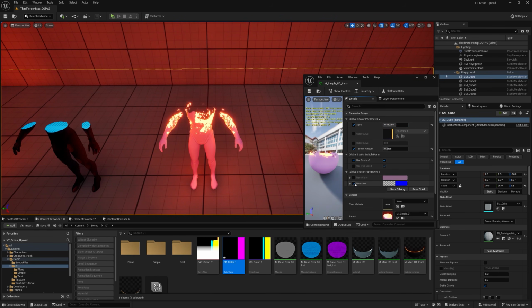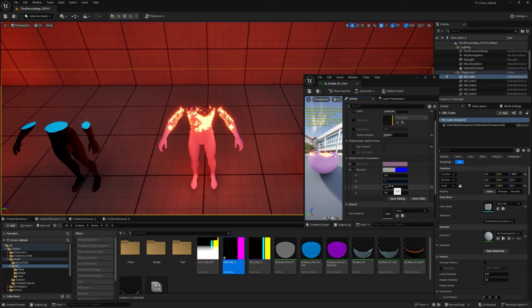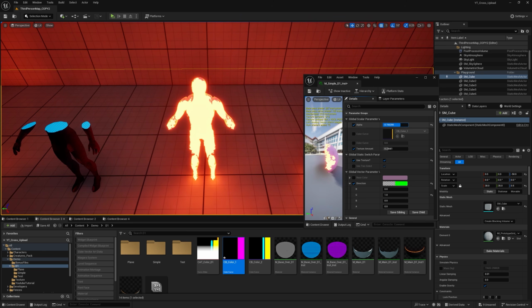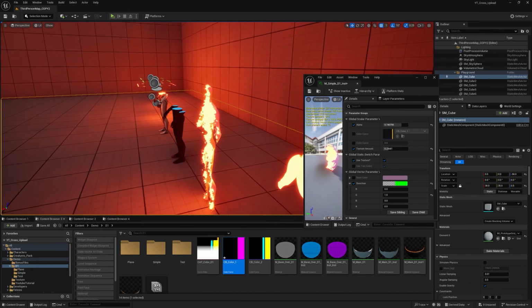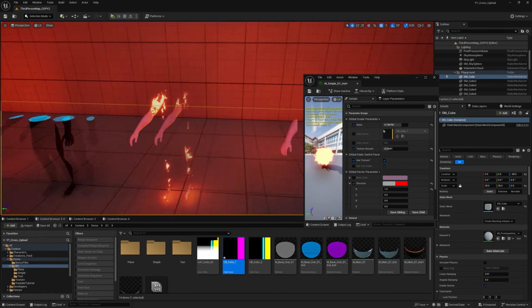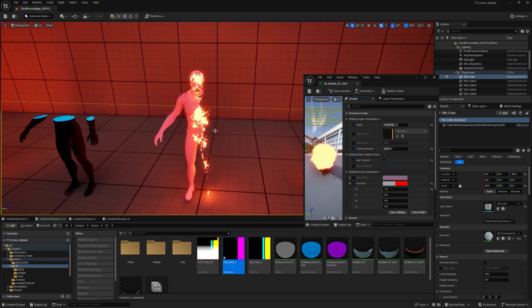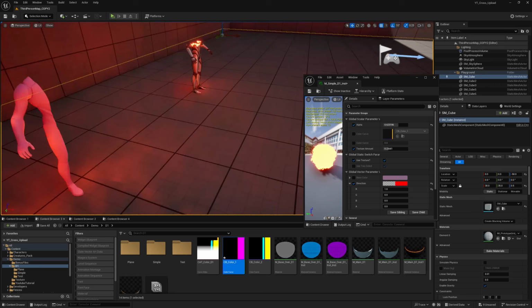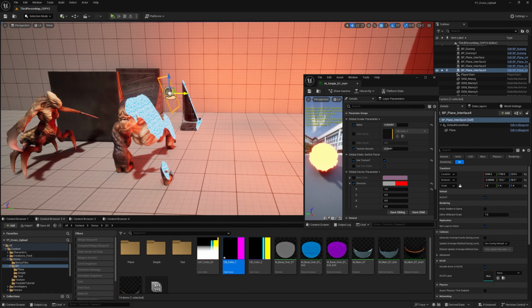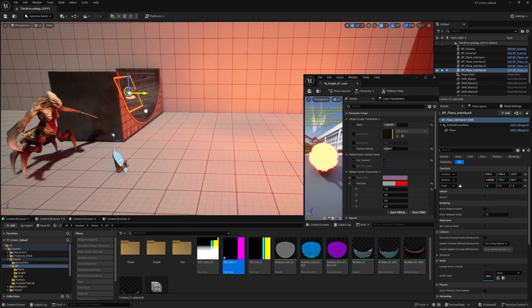And then here I can also change the direction. So here if I give 1 for green and 0 here for blue, I can cut it like that, like laterally like this. And if I change this to 0 and 1 for the R, I can cut it sideways. So this works without the plane like this one. You can just control the direction here without the plane, and you can control the dissolve amount with an alpha. You don't really have to move the plane around like this one.